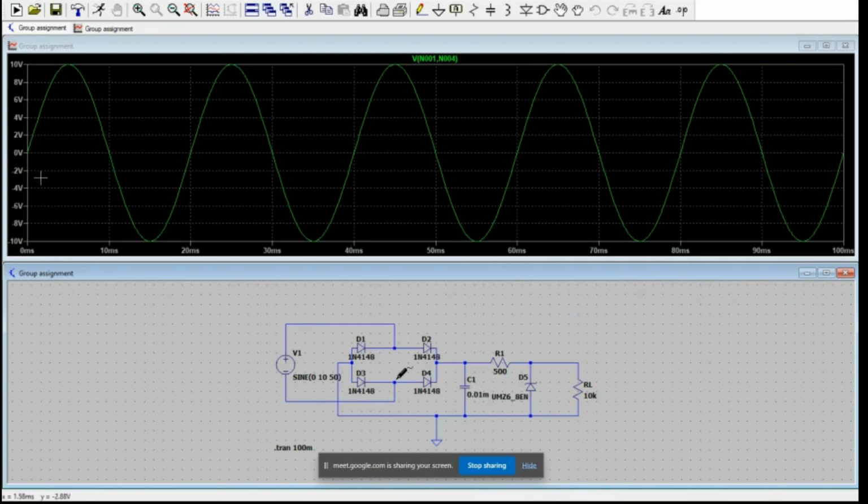This will be the waveform of the voltage produced by the AC voltage source. Okay, for the rectifier, the blue one will be the waveform produced because with a rectifier, pulsating DC is produced and the voltage will be mostly maintained on a positive side. Okay, the red one and the blue one will be the voltage produced by the rectifier.